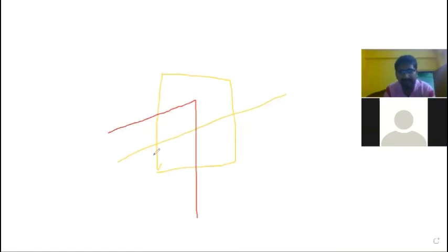Now, when we cut the section, this cutting line will be a chain thin line, and the two edges will be thick. Chain thin line, two edges thick. And when this cuts the material, what will happen? Here the material will be removed. So at this portion we get the hatching line. When there is a hatching line, this basically means the material is removed from this section.